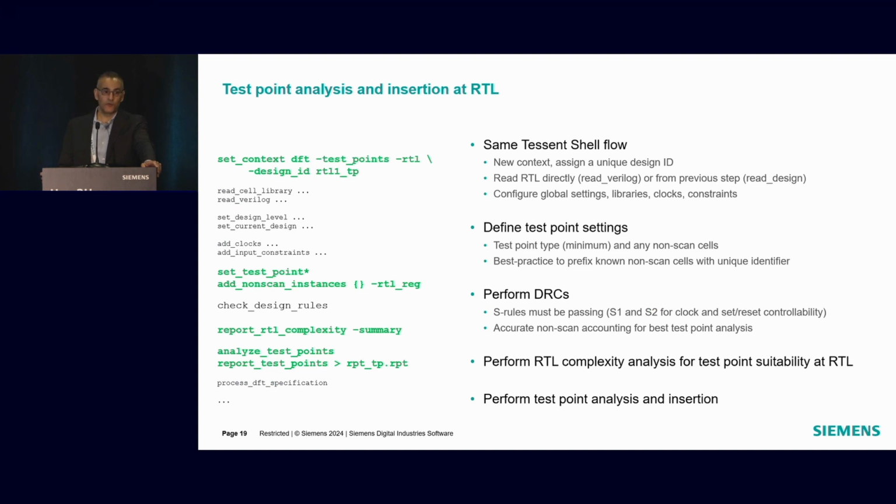And the same thing for our RTL test points. So we have the RTL test points, the test point RTL context here. And the set test point commands, you define where your non-scan areas are, where you don't want the tool to touch, and then report RTL complexity, which I mentioned just now, just to see how your design looks, analyze test points, report them, and then process DFT spec to insert them into the design.